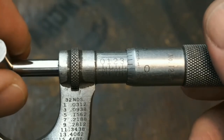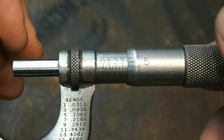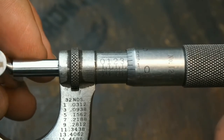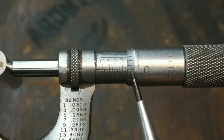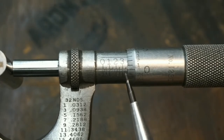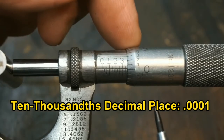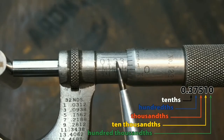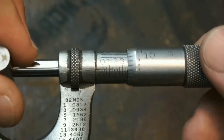Now, you also have tenths on this micrometer right here, which I can't really show you. I'm going to have to reconfigure the tenths there. So on the tenths, if you're past the 0, and it actually looks like we're past that 0, I'm going to say 1 to 2 tenths past that. You have to go up on the top of the mic to line up one of these numbers on the barrel to indicate how many tenths past you are, and we'll look at that as well.